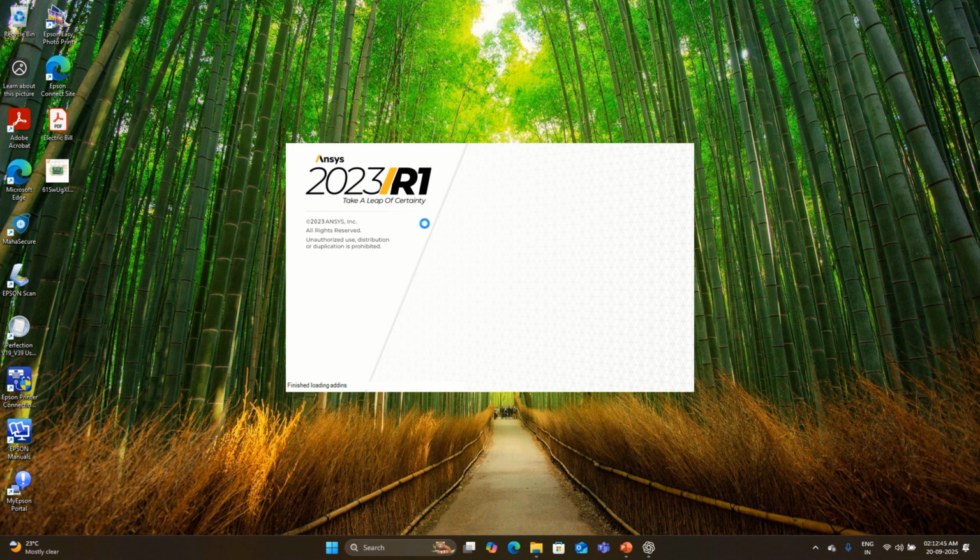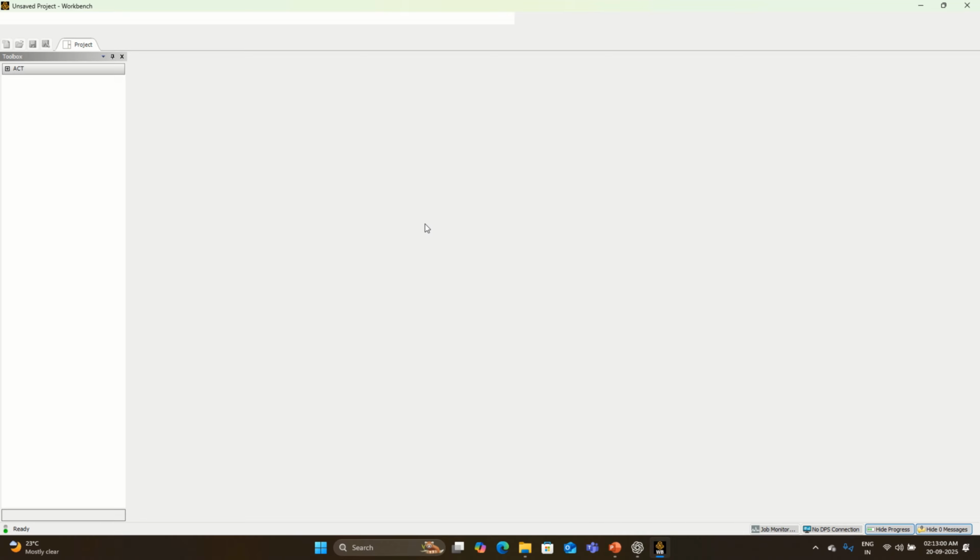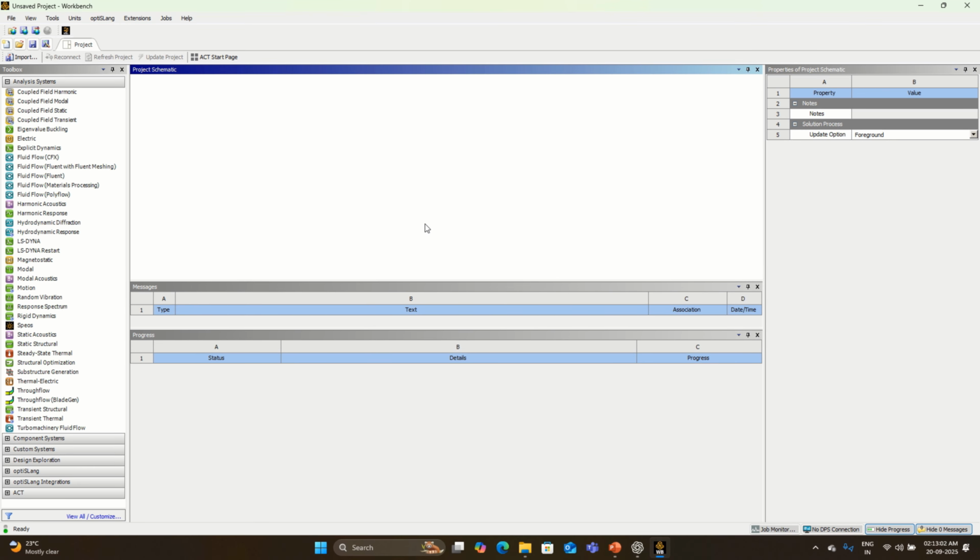Today we will see the CFD simulation of heat transfer in a heated circular tube. First of all, I will start with the workbench window. We will use the fluid flow Fluent model. The geometry preparation will be done with the help of design modeler. Then we will generate mesh and do the name selection, and then we'll run the iterations based upon the given boundary conditions. So let's start with the fluid flow Fluent.